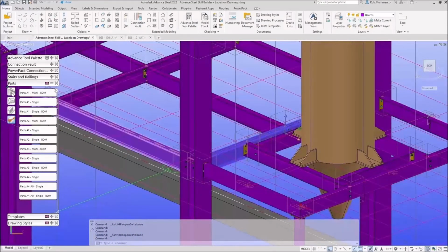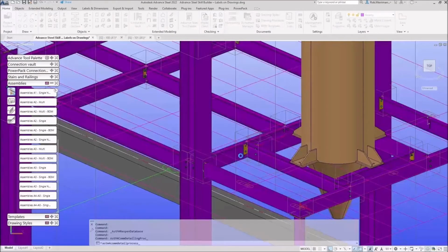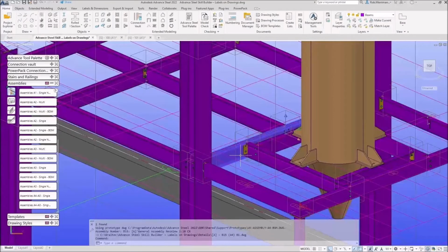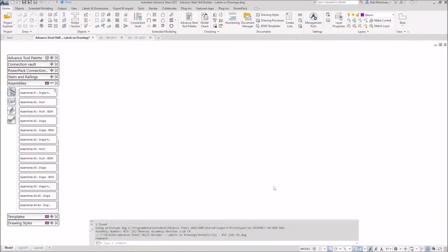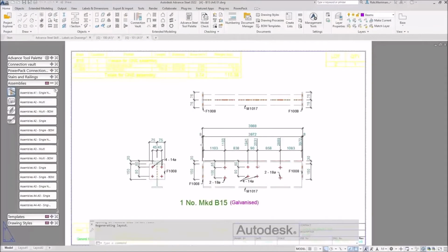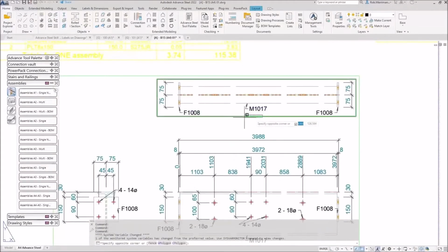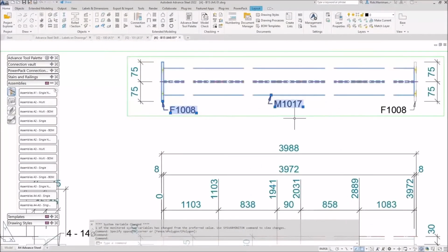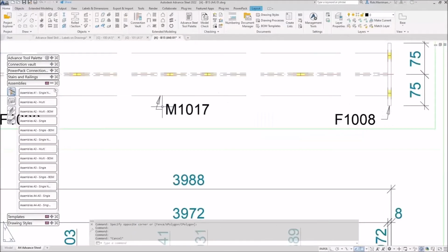let's run an assembly drawing because that default will work on all of the labels that the system puts on the drawings. So if we run an assembly drawing, and right click show assembly detail. So you don't have to go through the document manager if you know that there's something in there, but you can see in here now all of these labels have the horizontal length of 1.5.